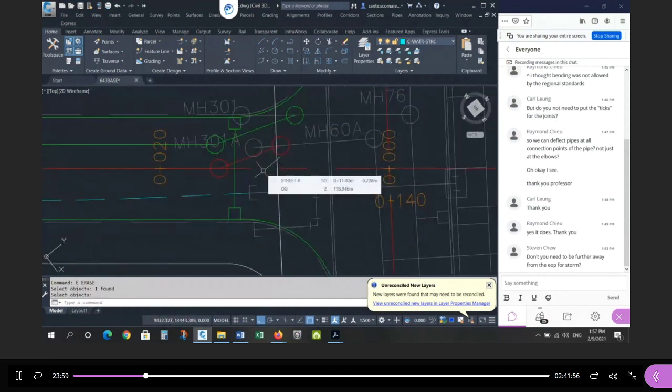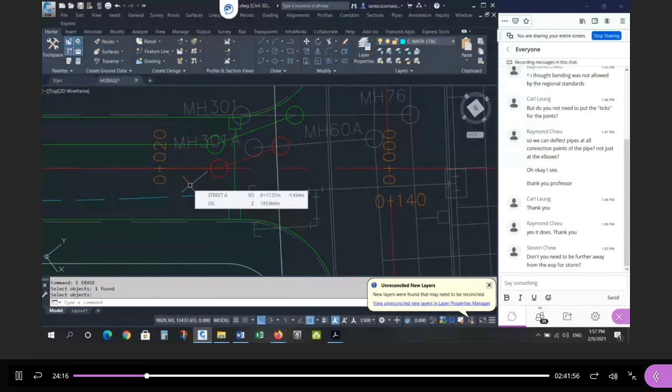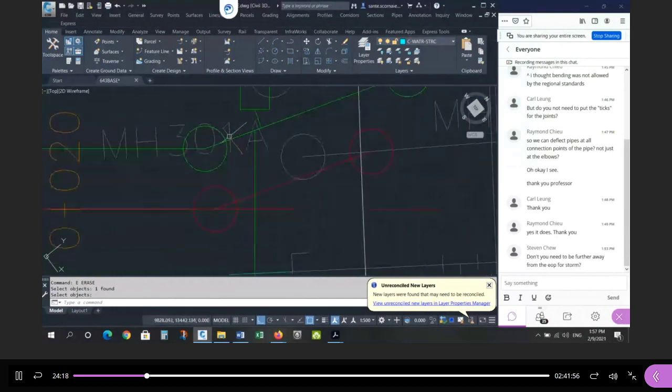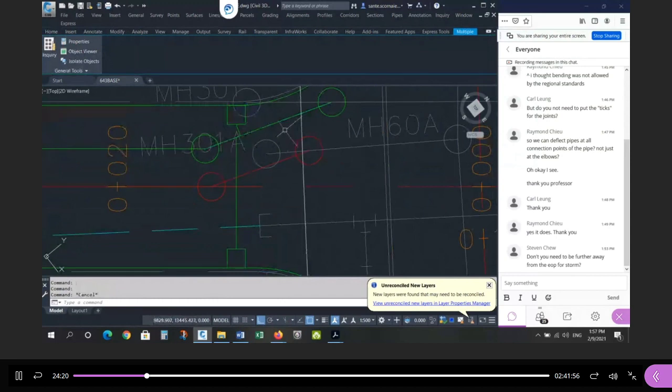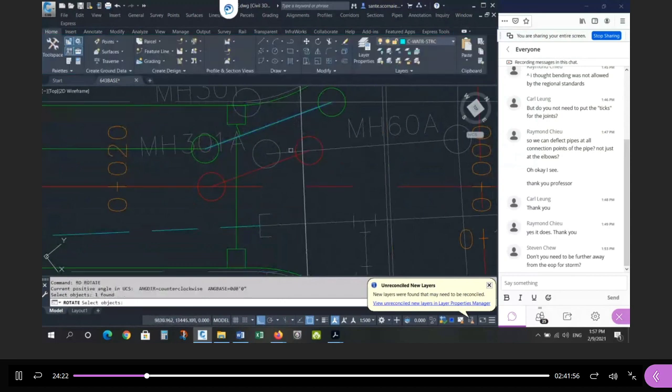So that's not a very good solution either. Okay. So again, whatever you did here, you didn't have the experience or the information from me thinking forward. Are the catch basins going to fit? I did talk about where the low point was going to be, but what does that mean to the hardware requirements? We're going to need catch basins at either end. So it is a little bit tight. If you think this is too close to this, then you can always rotate this and this about this center. You could always rotate the system this way.